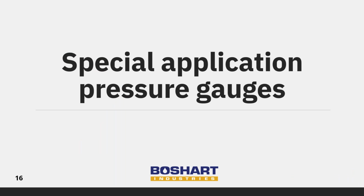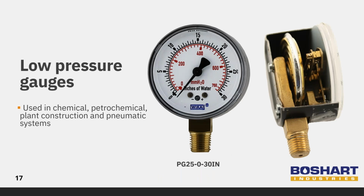Now we will go over the different types of special application pressure gauges available. Low pressure gauges are commonly used in chemical, petrochemical, plant construction, and pneumatic systems. Unlike other gauges, low pressure gauges have a copper alloy capsule type element and are printed with a dual scale. The outer black scale is in inches of water, and the inner red scale is in millimeters of water.